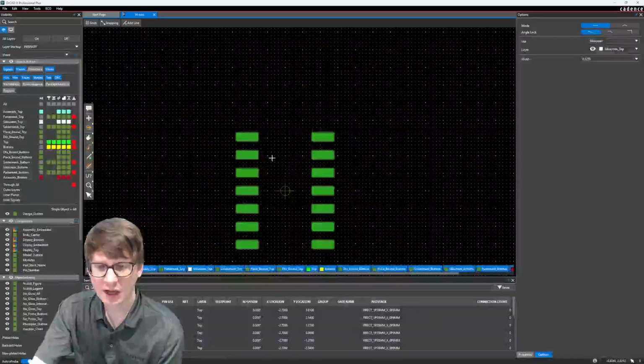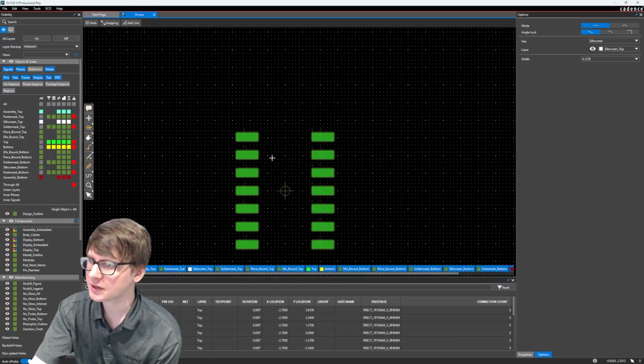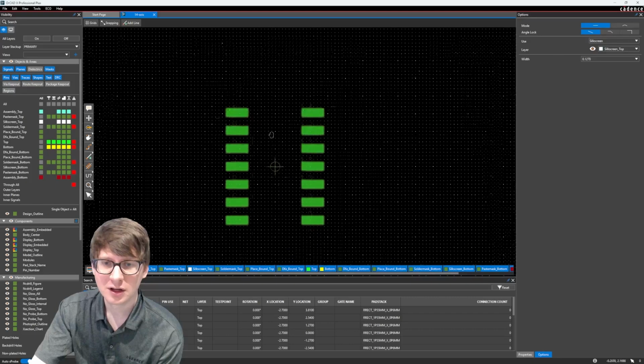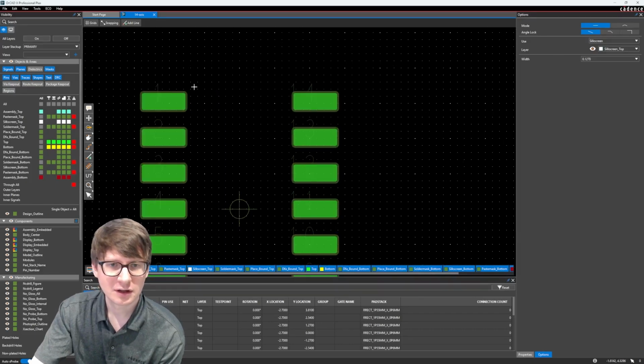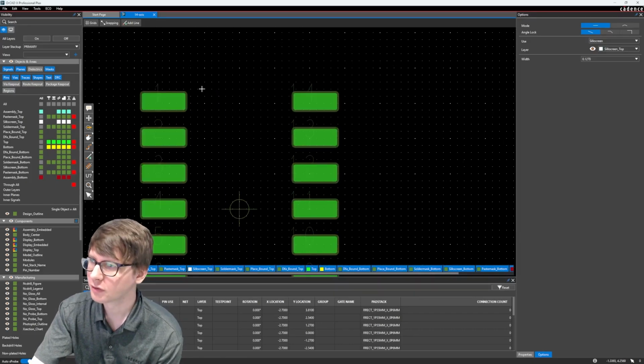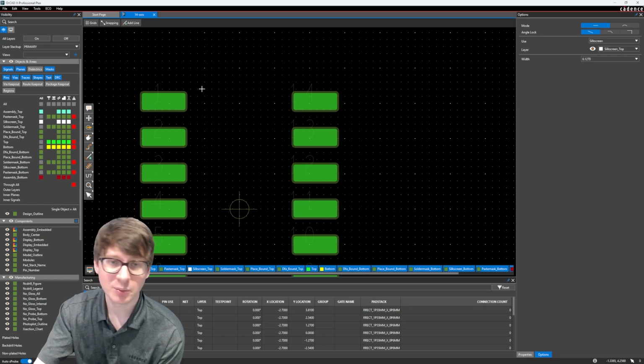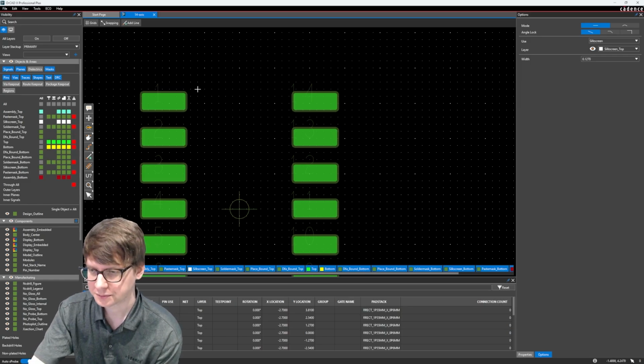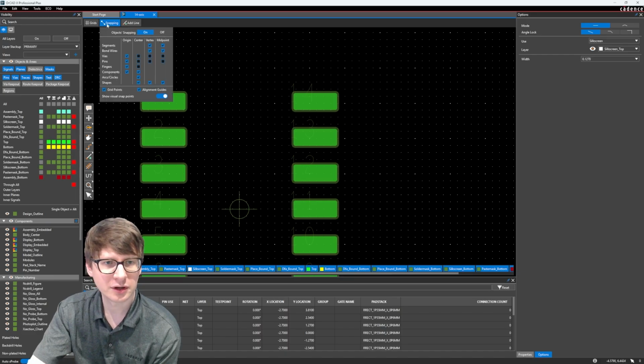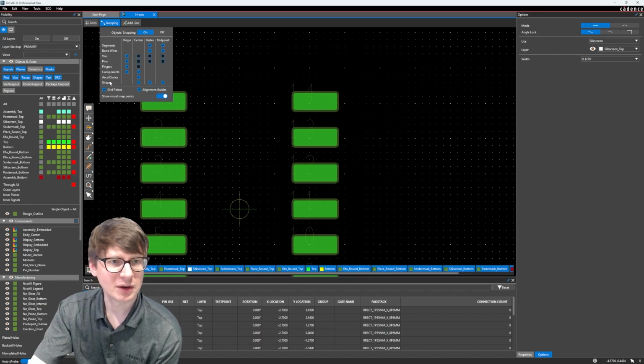And again, because our component is 8.6 millimeters tall, we're going to go ahead and measure out 8.6, so 4.3 millimeters, and that's where we're going to draw our line. Now, if we look at the bottom right here, we get a nice little indicator of what the grid point is that we're starting to draw at. And if we look at our snapping, you'll see that we are, I believe, snapping to grid points here.